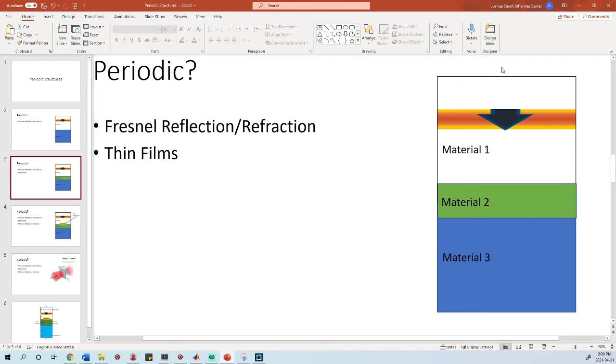So in the x direction, we want the light to travel to infinity. We don't want the light bouncing back into the simulation. We want the light to go off forever. So in the x direction, we want a PML, a perfectly matched layer, which will absorb the light going out so it won't come back in. So in both of the x directions, up here and down here, we want PMLs. Because our structure is periodic though, on this edge and on this edge, we want periodic boundary conditions.